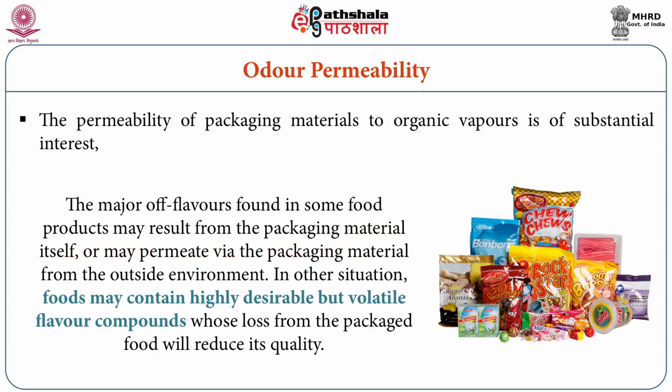The flavors found in some food products may result from the packaging material itself or may permeate via the packaging material from the outside environment. In other situations, food may contain highly desirable but volatile flavor compounds whose loss from the packaged food will reduce its quality. In both situations, suitable tests must be undertaken to select materials which have the desired odor barrier properties.